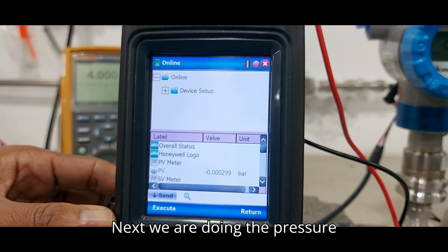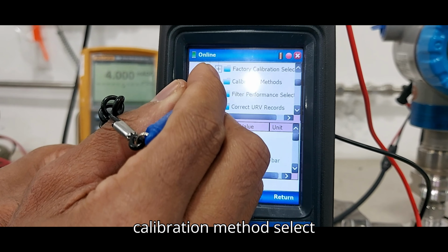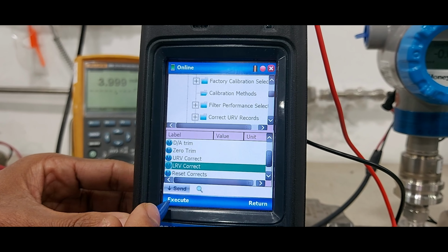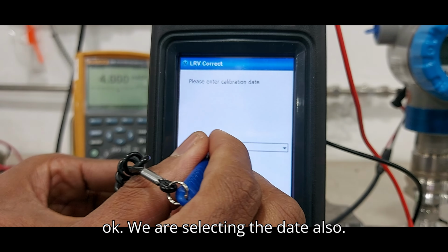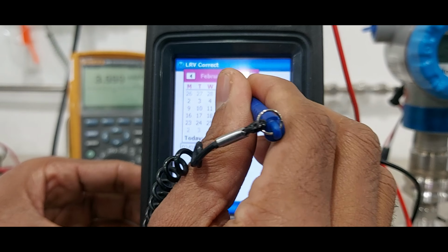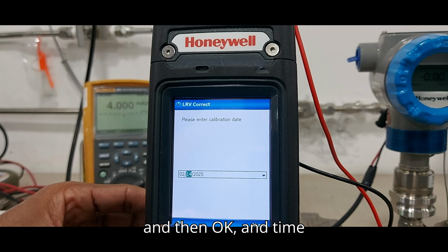Next we are doing the pressure calibration. First select the device setup, select the calibration menu and the calibration method. Select it. First we are doing the URV correction. Select it and execute. Then press OK. We are selecting the date also. Date, time. First enter the year. Year selected, date selected, and then OK.